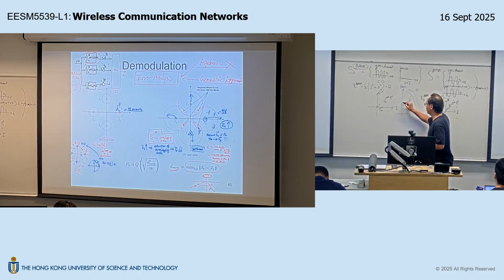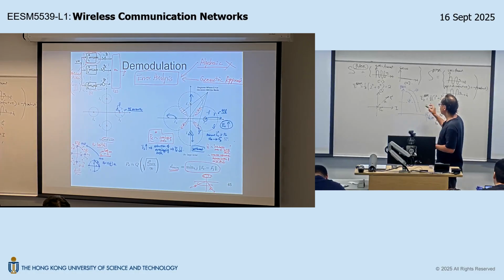Well, what we have done is to achieve the same error probability, one design requires less symbol energy than the others, right? So which one requires less? BPSK requires less, so this would be BPSK, right? And then the other one would be BASK, amplitude shift keying here, right?